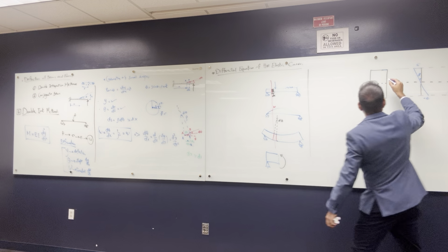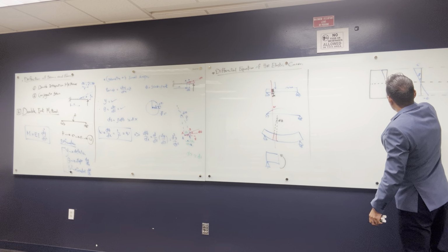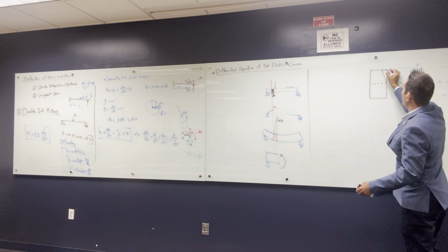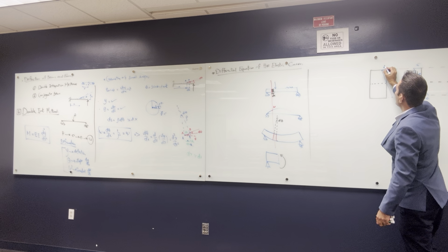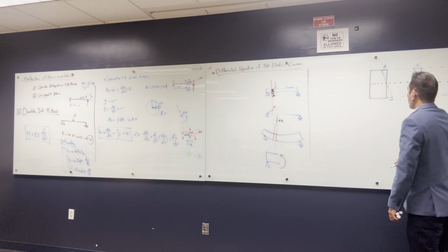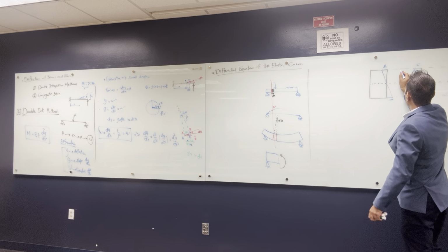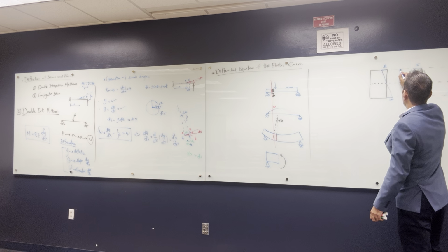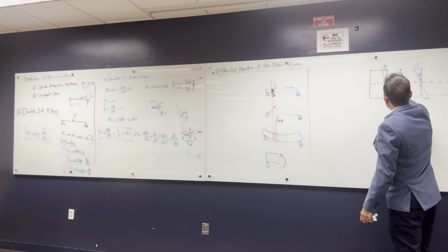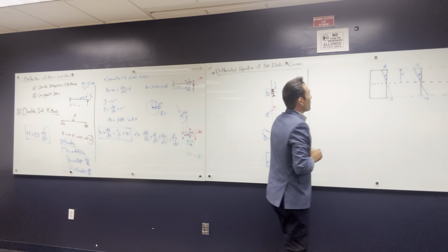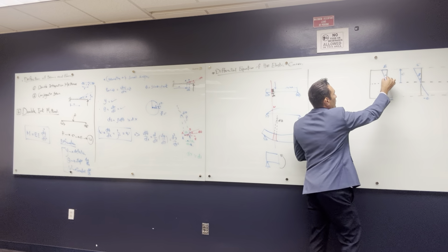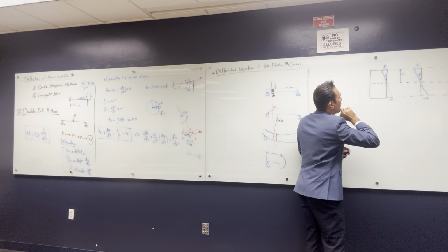All right? So you are gonna have this until you come to the neutral line, and then it's gonna be tension or elongation. Like here is compression, and let's say that the compression is DL, like this section went DL this way and negative DL the other way, all right? And let's assume that the distance from this neutral line to the top is C, okay? All right, and definitely the angle here is d theta, which is the difference between this line and this line, all right?